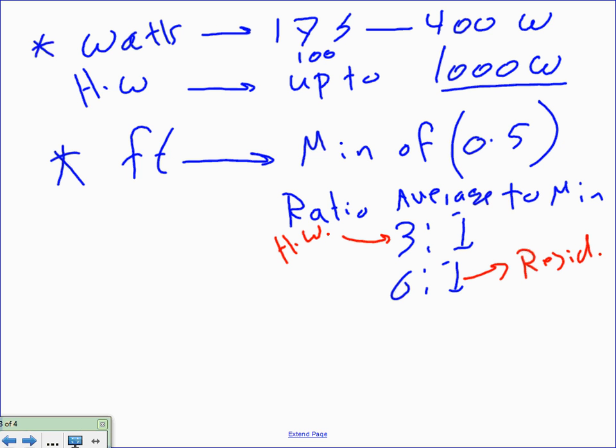If you do highways, they can put 1,000 watt luminaires, guys, in these big towers, 75 foot, to light the whole area. You can use metal halide most of the time, or high pressure sodium. These are the 2 fixtures commonly used in highways and roads. Metal halide, high pressure sodium. So this is just a couple of watts that you can pick from.